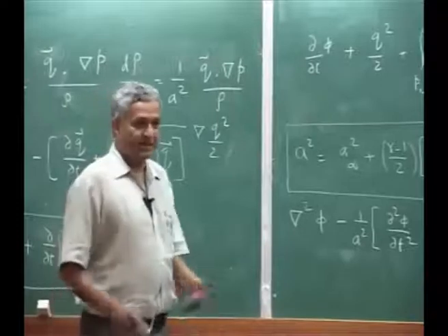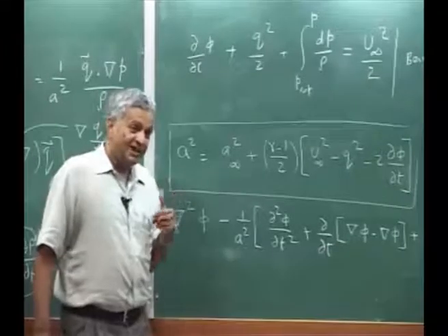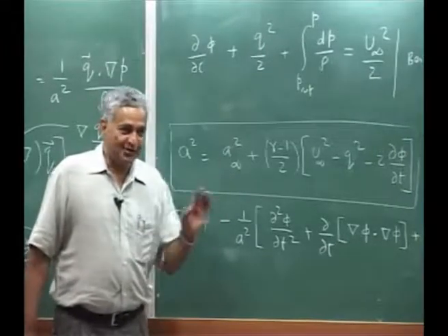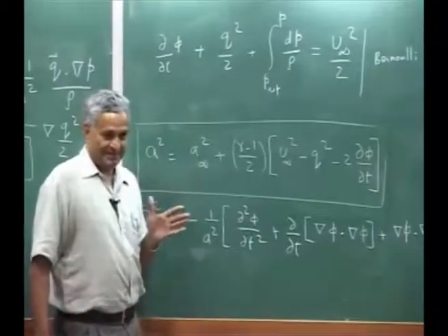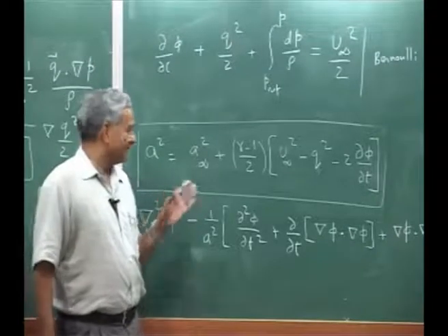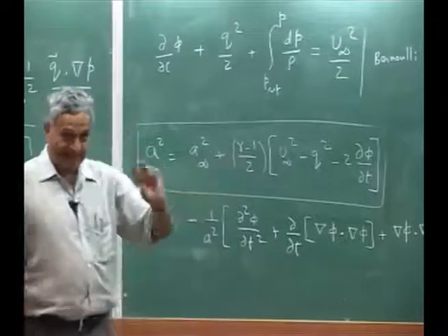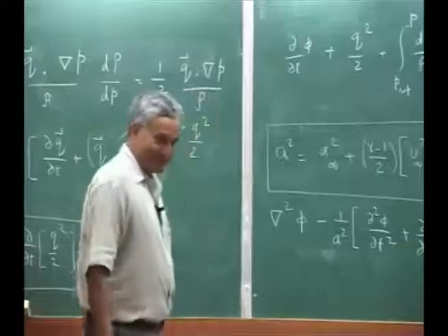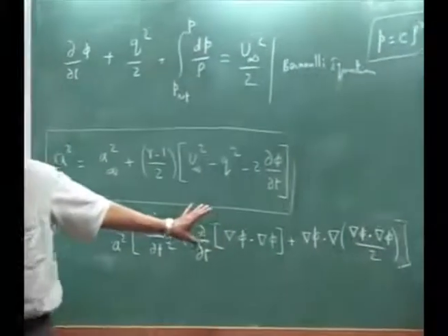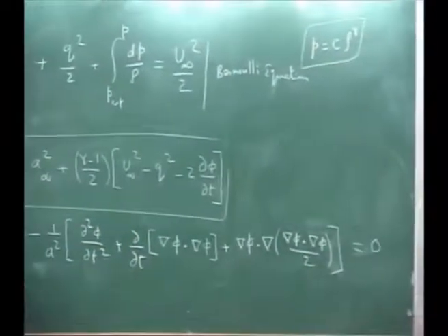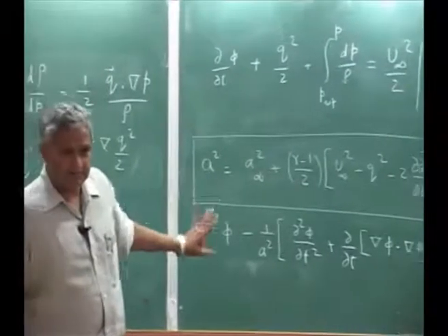Okay. But if it is a compressible flow, once you go, then you start. That is why transonic. When you go to transonic speed, you cannot assume my Mach number is approaching 1. You cannot make that my speed of sound and the vehicle, they are almost close. I can't make that assumption. Okay. Then basically I have to use the full nonlinear equation. Now what people do is, even in transonic, because this is fully nonlinear, you cannot get a solution. It's not easy, you have to do numerical only.